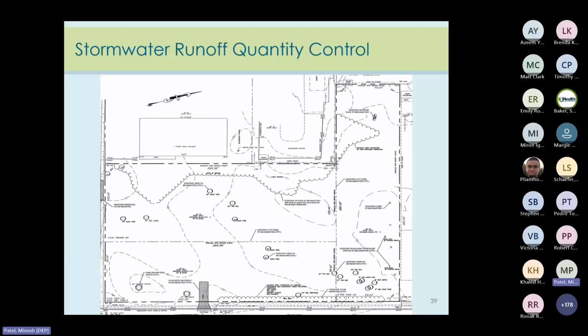So here's an example site. The flow was evaluated as sheet flow directed primarily in a southerly direction. However, we received complaints of flooding along the road lying to the east of this project and from the area northwest of the project. It was determined that the drainage areas were not delineated correctly. Whether or not that was due to an incorrect evaluation of the topography, that's unknown, but this shows why it's important to properly evaluate it and delineate drainage areas.